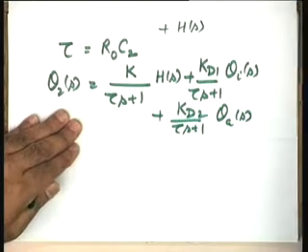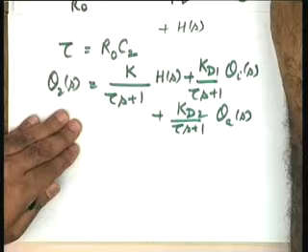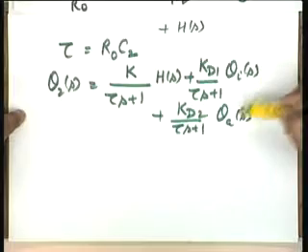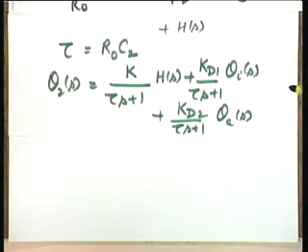I hope this will be all right. Make an attempt, please. Some suitable constants K, Kd1 and Kd2 I define, and in terms of these constants this becomes my equation. θ2 is the output variable, H(s) is the controlled variable, and θi(s) and θa(s) are the disturbance variables. Okay?